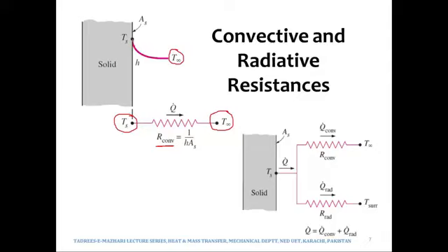And you can see over here that this is the temperature profile. Ts is greater than T infinity, so that is why temperature is higher at Ts and lower at T infinity. It may be the other way around. If T infinity is greater than Ts, then heat will flow from T infinity, from the fluid into the solid wall.